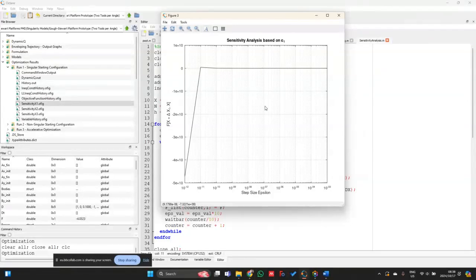And anywhere along this constant line, you can then go and select your step size value. So that's why in this case, it was 10 to the power of minus 8. So it's more or less in the center of this constant line that I have over here. If I can go a bit finer, that's also fine. So 10 to the power of minus 9, minus 10 is maybe stretching it a bit.